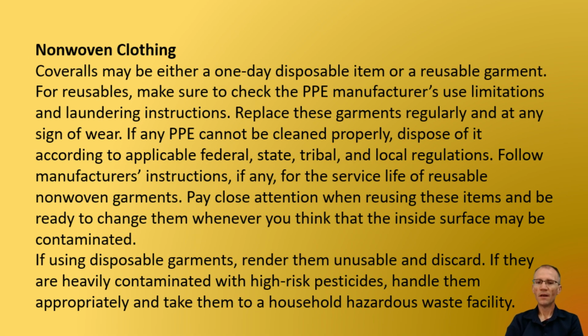Non-woven clothing. Coveralls may be either a one-day disposable item or a reusable garment. For reusables, make sure to check PPE manufacturers' use limitations for laundering instructions. Replace these garments regularly and at any sign of wear. If any PPE cannot be cleaned properly, dispose of it according to applicable federal, state, tribal, and local regulations.